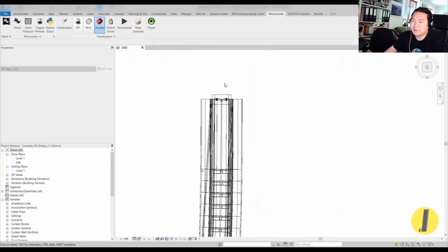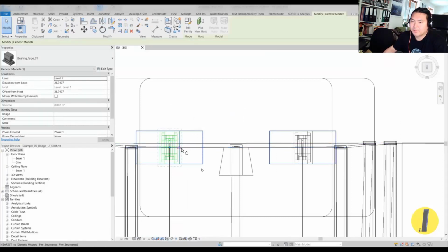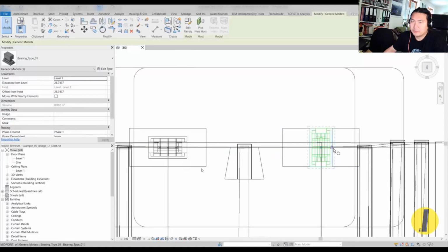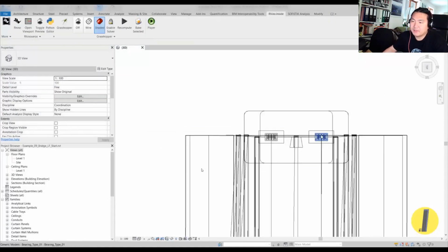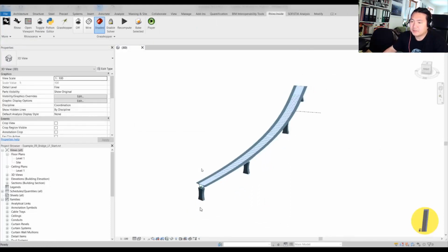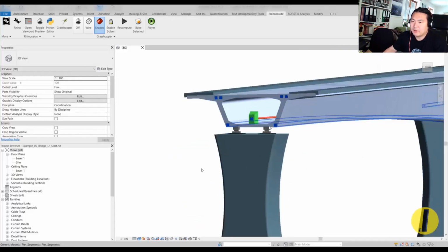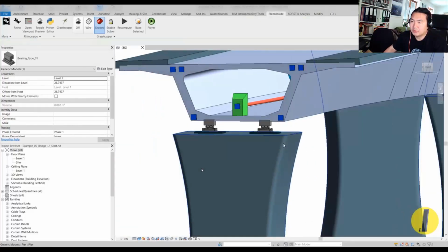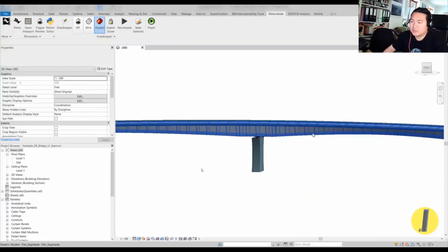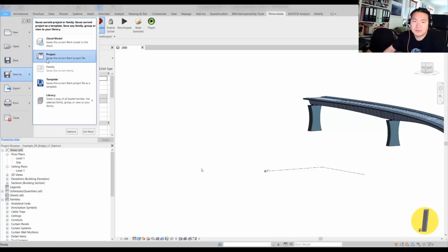Probably it's better if you have more than 20 of them, so you don't have to manually go through all these elements. Or we could also set in the Revit family a certain rotation angle. I could have measured the angle of rotation and then put that attribute in the family, and the family would have the rotation angle value within the Revit parameter.